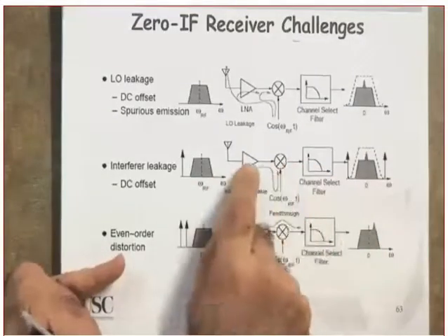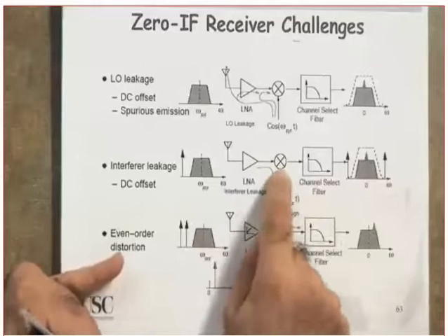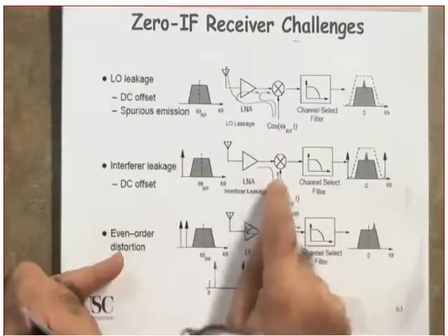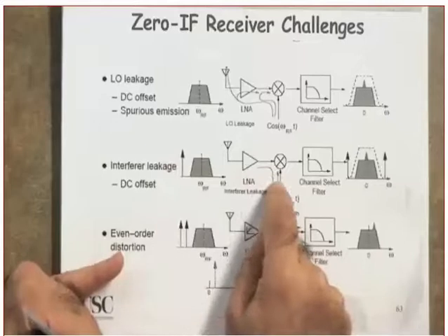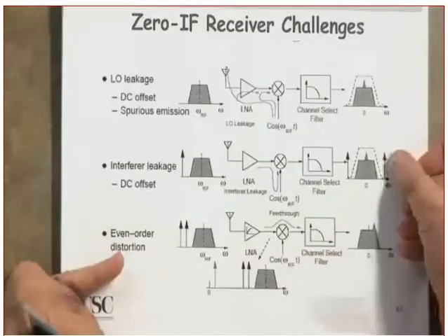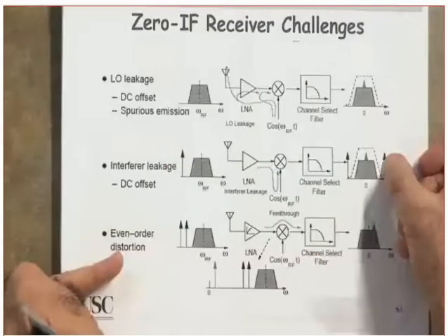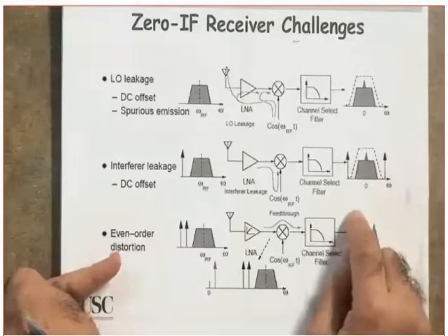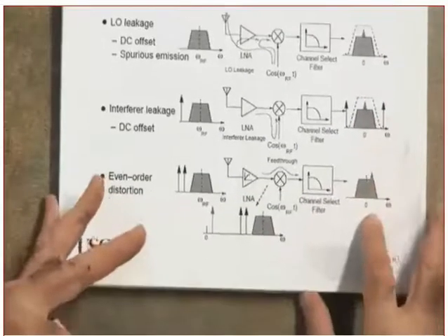Now, could it also mix with the RF? Could it mix with the RF? It could mix with the RF, generating maybe these components. Are you following that? But I don't worry about them. Why? Because I'm going to use a low-pass filter in here. Clear?